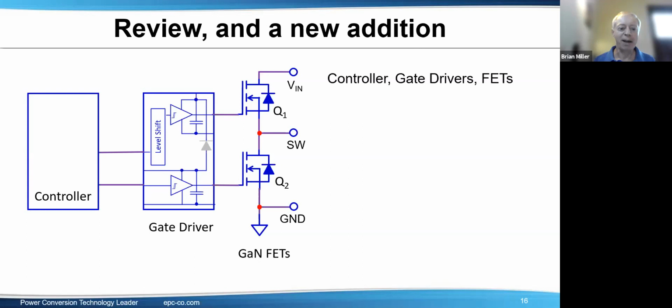Now we do add small Schottkys in parallel to reduce the voltage when using a MOSFET gate driver, but that's only like a 1 amp diode. The purpose is to reduce the voltage during dead time. It's not really for efficiency. I think one of the EPC apps engineers said the efficiency is about the same either way. So to keep the bootstrap and the negative voltage on the switch node under control is more the goal.